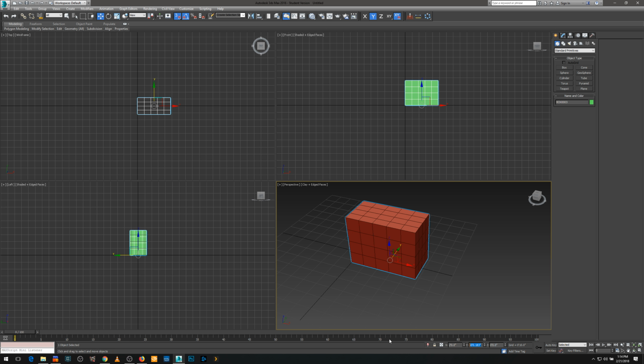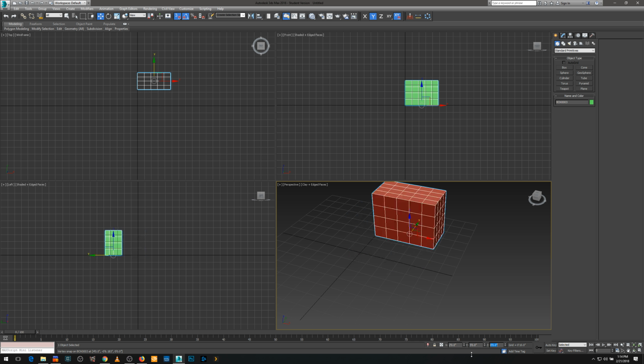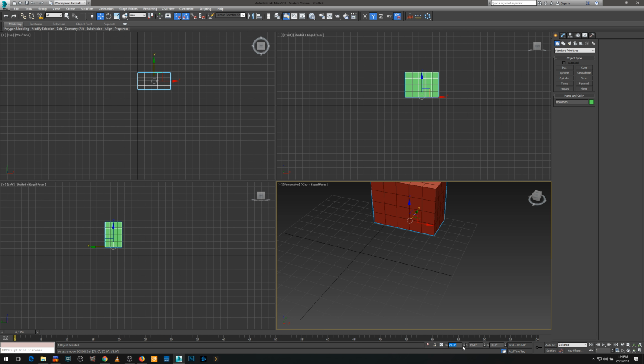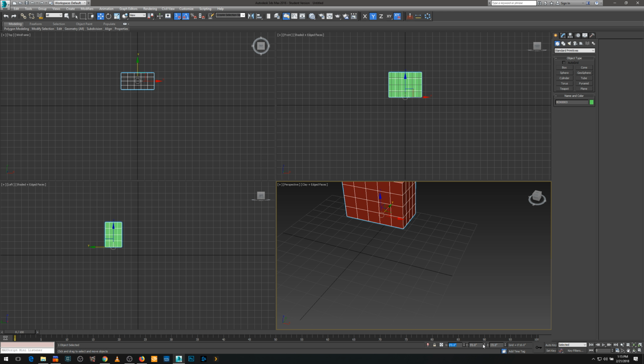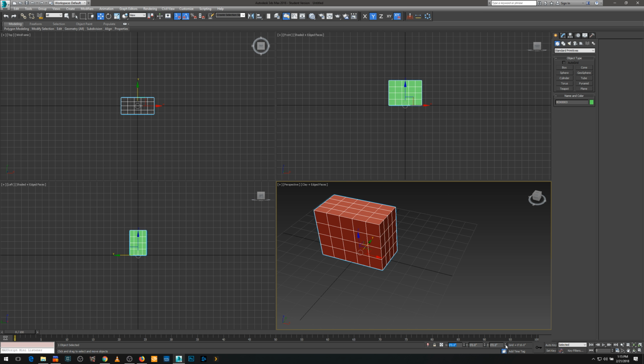And I will move back on the y-axis, so watch the top or this perspective grid, and I'll type in 3 for 3 feet. Moves it back, and if I want to move it up in the air 1 foot, there's the z-axis. I can move it up in the air 1 foot, so you can see it here. Now, if I don't want to do any of those things, I could right-click on the arrows to zero everything out, or I could type in new values. I'm just going to right-click, and everything is zeroed once again.